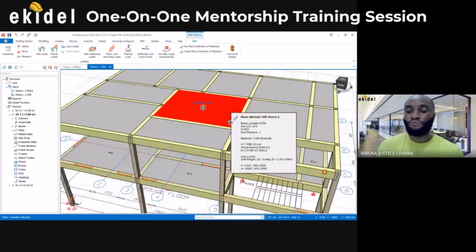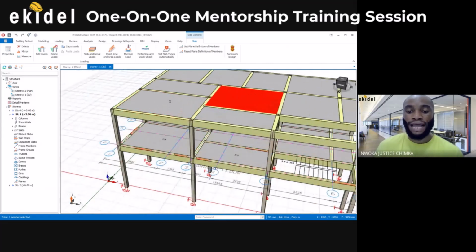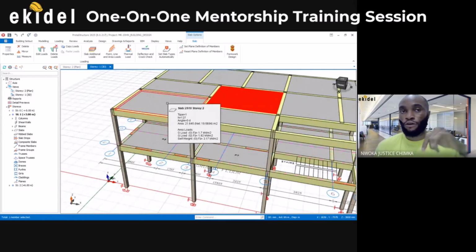So right now, if we want to use a concrete slab, then we can choose to reduce the load on the slab. Because for example, if this is a roof beam now, we don't need that imposed load to be 1.92 again. At least we should reduce it. Because right now, there is not much happening here, except maybe you have a tank that will sit on the roof. So at that place, they can now choose to apply an area load, which is the tank load, right? That will carry a water tank at the top there or something.